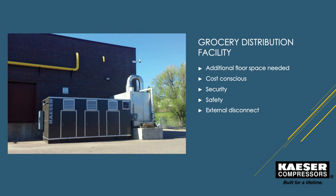As Neil mentioned earlier, the side that we are seeing here is the exhaust side. The dampers shown are the exhaust side, and the panels below those are for major service or removal of the individual compressors. The intakes would then be placed against the building, so we do not have any recirculation of heat back into the package.